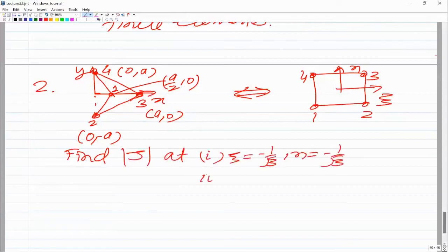Point number 2. Actually, we expect the area ratios to be positive, but you see the element is too much distorted from the rectangular shape in the physical coordinate space, so this determinant J may come out to be negative, which is undesirable. Therefore, when you do the meshing, you have to make sure that the elements are of proper shape and size. They should be close to square, and basically that is the ideal thing. But then there are some allowable limits.